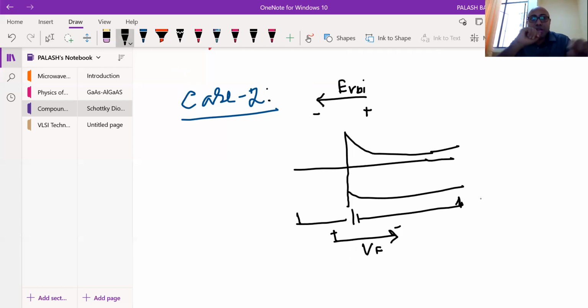You are connecting one terminal, which is the ground terminal, to one of the probes, and the other terminal, which may be positive or negative, to the other side. What I'm trying to tell you is, if it is a two probe measurement, a two terminal measurement, you are not really giving negative or positive. You are actually doing everything with respect to ground potential.